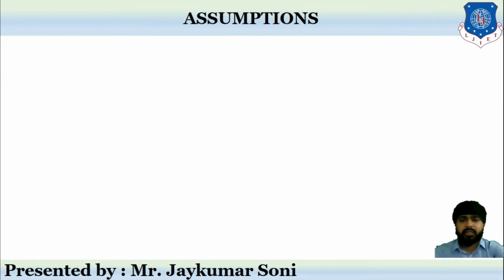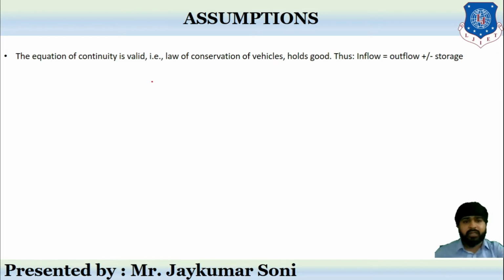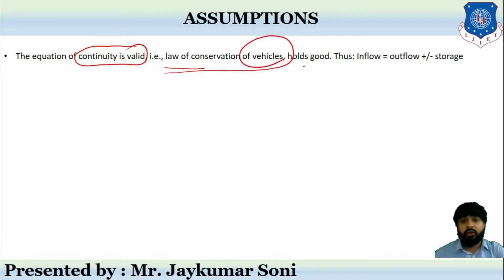There are assumptions that they have made. What are those assumptions? The equation of continuity is valid. They thought that, just like the law of conservation of energy, a law of conservation of vehicles also holds good for this theory. That means inflow equals outflow plus or minus storage. This is what they have considered.